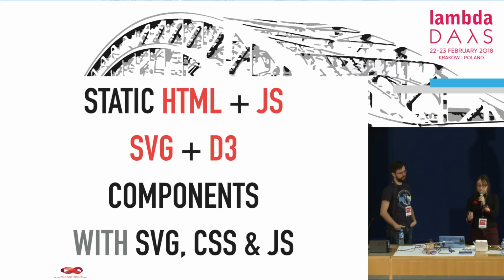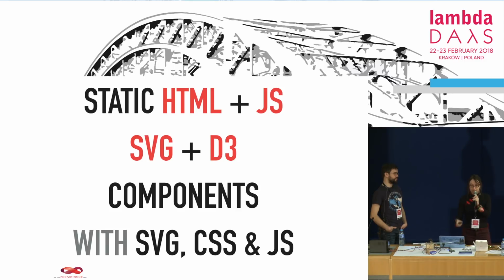And so this is what happens when you connect. The GRiSP development board has an IP, and you can connect to it, and there is a web server on it. So this is what you get: a static HTML, and then you get the JavaScript and the CSS, whatever is on it, and then the components are made in SVG, and D3 is getting the information from the web sockets, and then updating the information in the SVG.